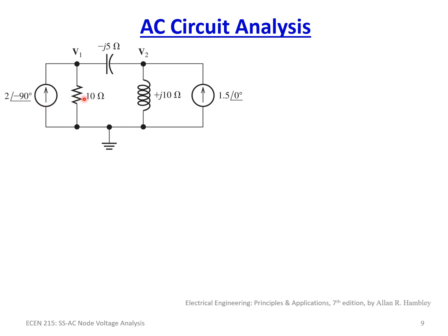The resistor stayed the same, 10 ohms. And we have a capacitor that was 2,000 microfarads. Let's convert that over. We got minus j over omega C, and that gives us minus j5 ohms. For the inductor, it was 0.1 henries, and it's j omega L. So we end up with j times 0.1 henries times 100, which is plus j10. So that's how we have all the impedance values, and we have redrawn our circuit here exactly now in terms of impedances.